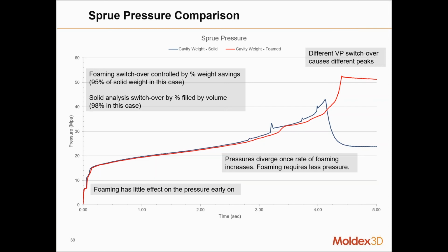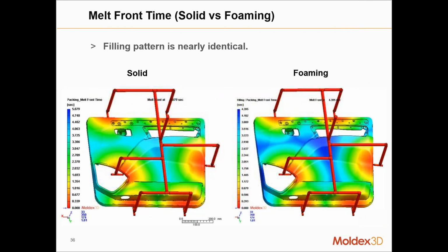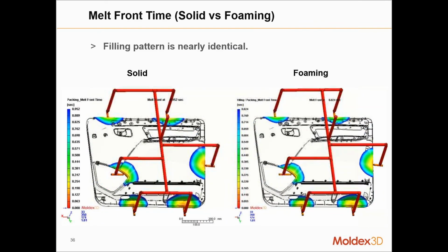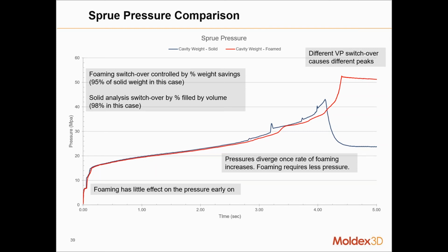And that is, if you paid a little closer attention to the flow front progression, also because of the kind of structures you have, holes or grill structures, that is causing some sort of hesitation in flow, because the foam has to push your melt front forward, which is not as easy to do. So the pressure is going up in trying to fill those hard to fill areas. And the interesting thing is, as your pressure goes up, the actual foaming goes down. I will be showing you that in one of the following slides.